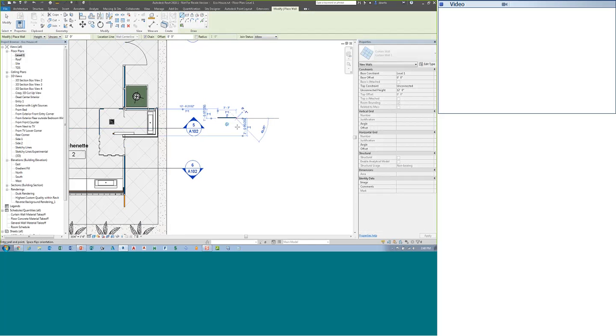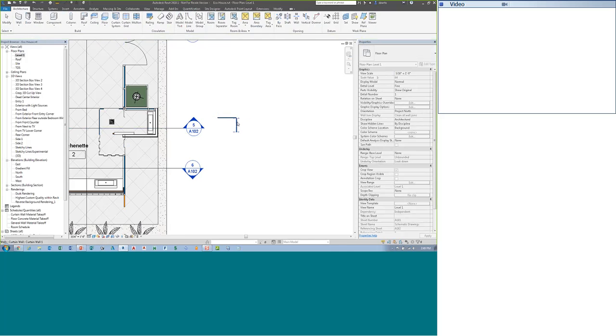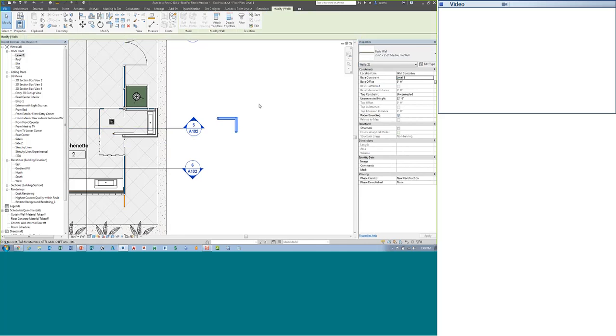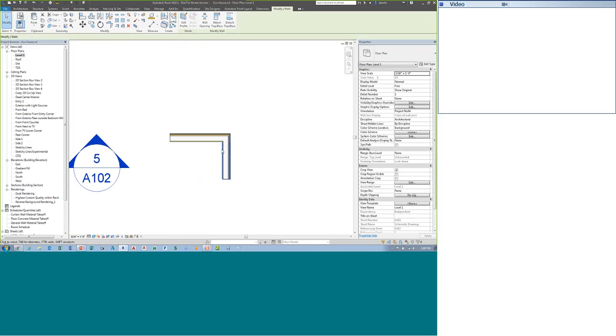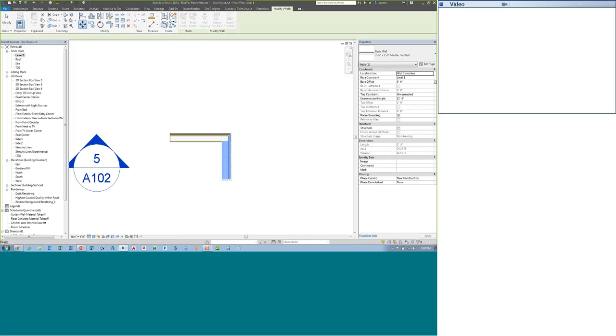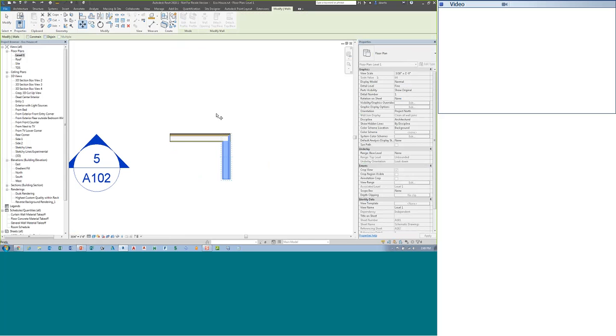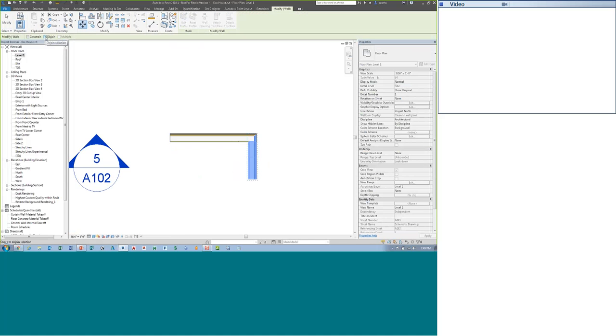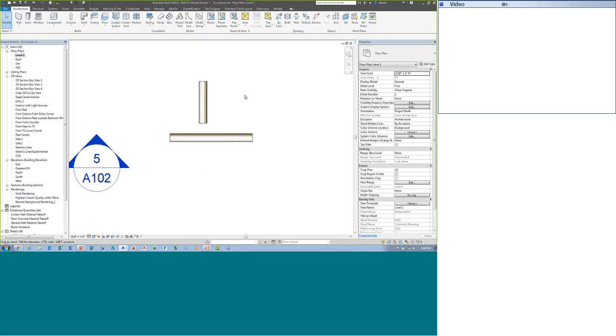The same functionality occurs, and a lot of people use it when they're working with walls. And we draw a wall like this. Oops, let's not use that wall. Let's use standard walls so it's easier to see. Okay, so if we look at this wall here, if I select this object and I move it, by default it moves it where it is joined, and it stretches the other wall and keeps them connected. But if I use the Move command and I check Disjoint, it will break that relationship. Okay, so that's the Disjoint feature.